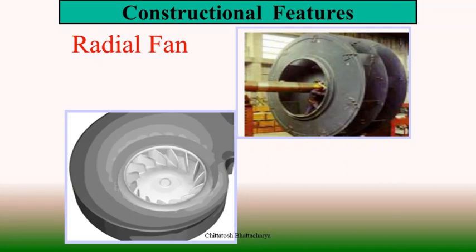Involute type of casings are used for centrifugal fans, and this involute casing gives the flow pattern from axial suction to radial discharge, and gradually there is a control mechanism also. We have inlet guide vane based control as well as discharge dampers.